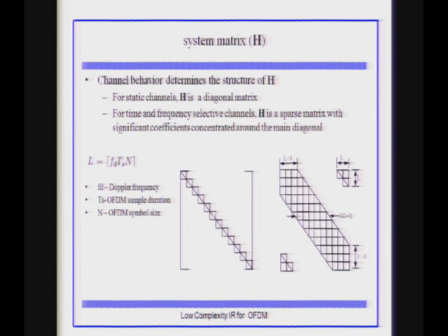Say the large-sized OFDM systems like DVB-T2, the second generation DVB, we are talking about 32K FFT. So there the N is so high, and TS being so small, some 7 over 64 microseconds or whatever. So this term could be high. So even with a low Doppler there, now you can have a high L. So that is one example.